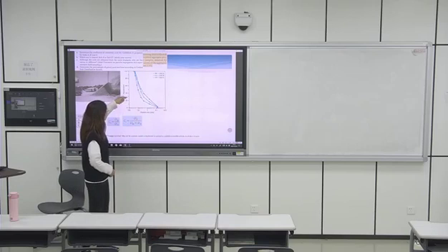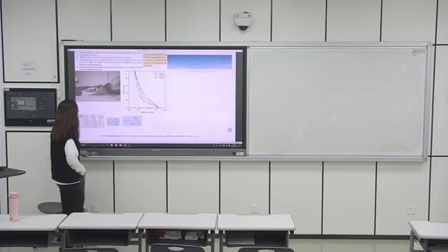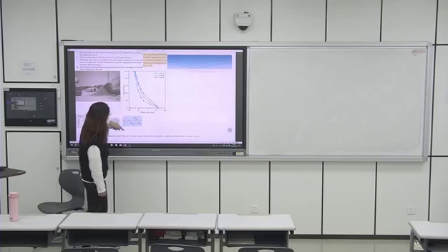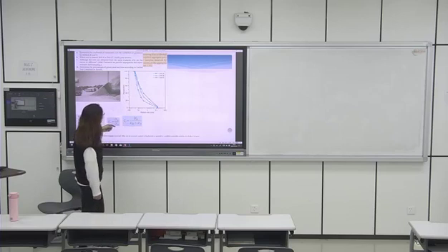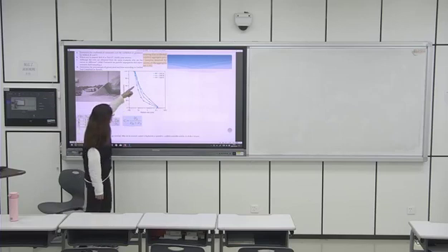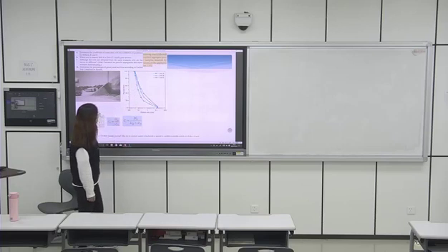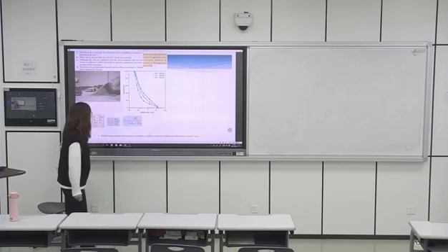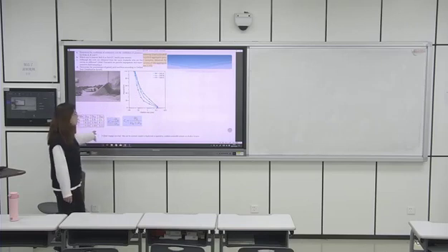And then 30, let's see in here, it is maybe around 6 or 7. In here it is 5. And then 60, it is maybe around 21. It is around 21. Right? No, it's not 21. It should be 11 something. Right? I gave the wrong answer. But this is the way to find D10, D30, and D60.